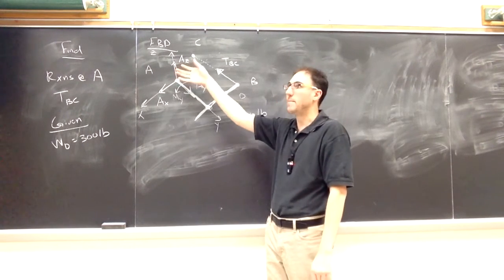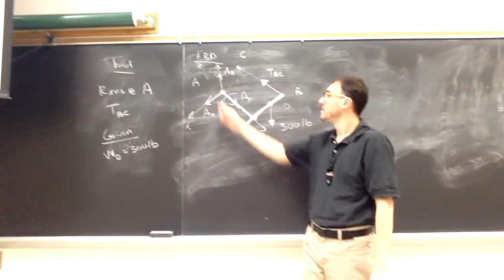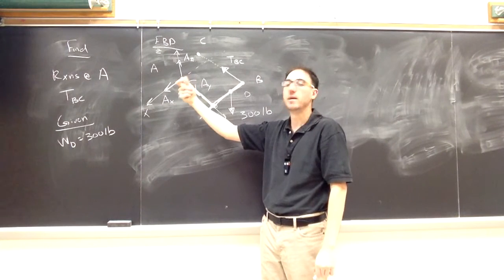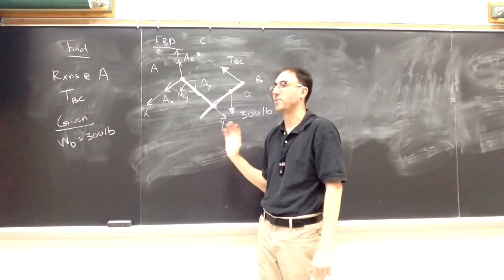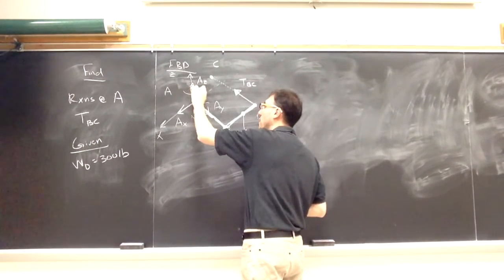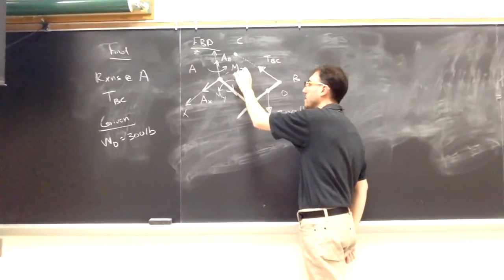Around z, we have the same issue. Can we twist it around that z-axis? If we try to do that, again, that pin is going to hit the bracket and prevent that from rotating. So it cannot freely rotate around the z-axis at A. So there's also going to be a moment, I'll assume, around the positive z-axis. I'll call that Mz.